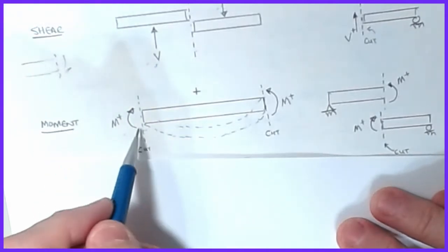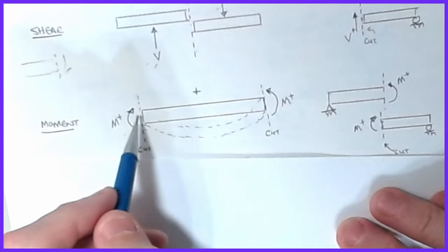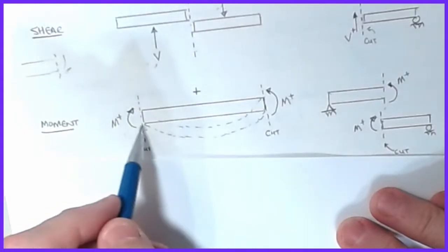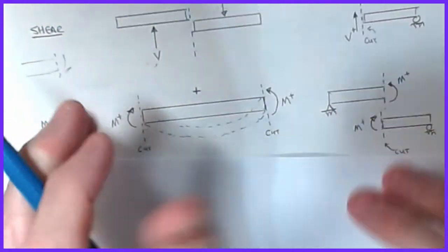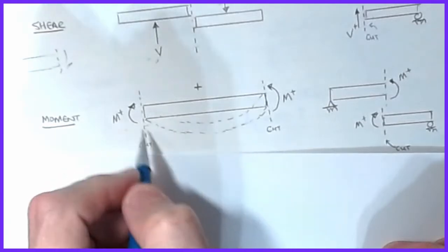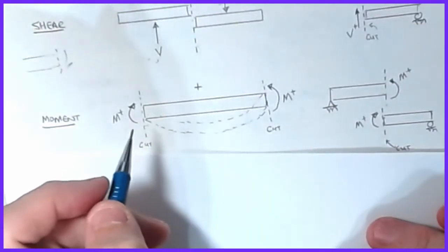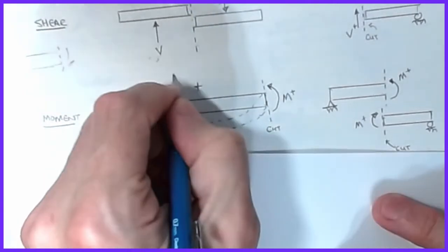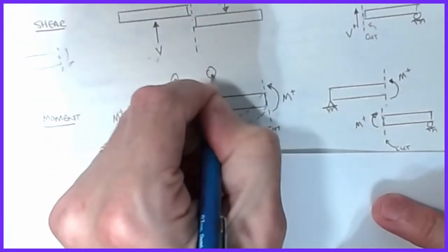All right, so if I imagine this beam, and I know in statics we say everything is rigid, but if we were allowed to let this beam deflect under these rotations on the end, and I take the end of this thing and bend it that way, clearly it's going to start to bow down. All right. And so all we have to do is draw this deflected shape and put a positive up here and draw two eyeballs here.